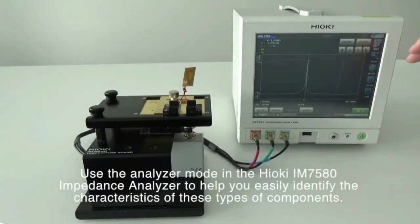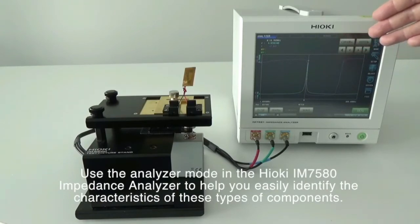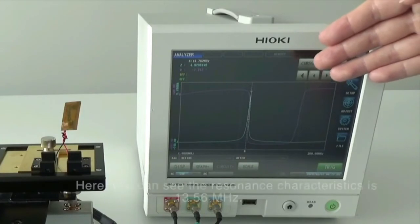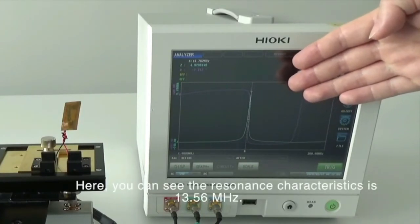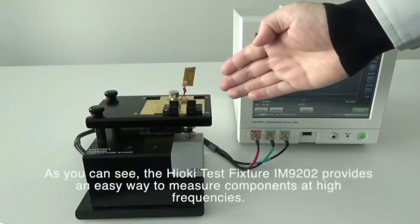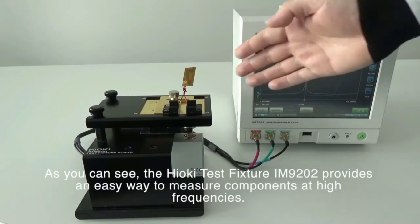Use the Analyzer mode in the Hioki IM7580 impedance analyzer to help you easily identify the characteristics of these types of components. Here you can see the resonance characteristic is 13.56 MHz. As you can see, the Hioki test fixture IM9202 provides an easy way to measure components at high frequencies.